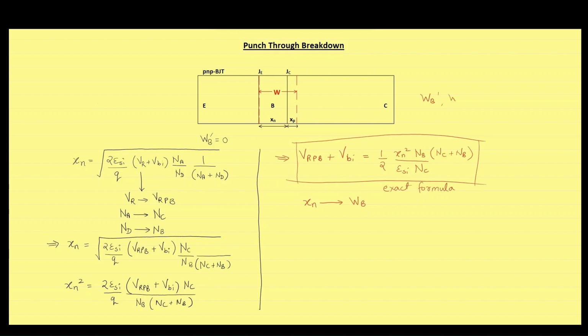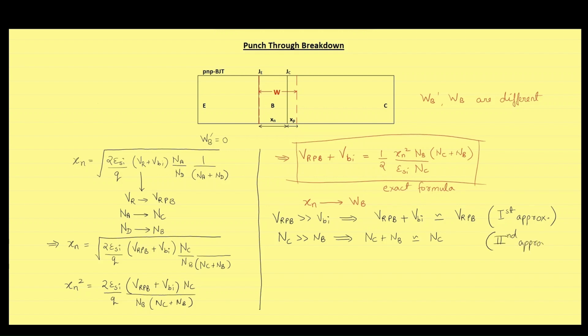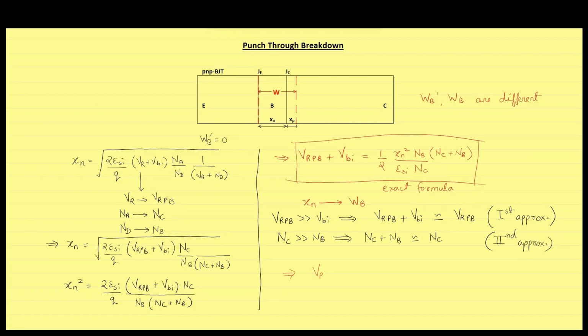Remember that base width and effective base width are different parameters. As you are aware, in this subject, there are so many approximations. And here also, we have a few approximations: the reverse bias voltage corresponding to punch-through breakdown is significantly greater than the built-in potential. Therefore, while adding these two terms, we can ignore the built-in potential. Similarly, we know collector concentration is significantly greater than base concentration. Therefore, while adding these two terms, we can ignore the base doping concentration. Therefore, the above formula for reverse bias voltage at punch-through breakdown will modify to...